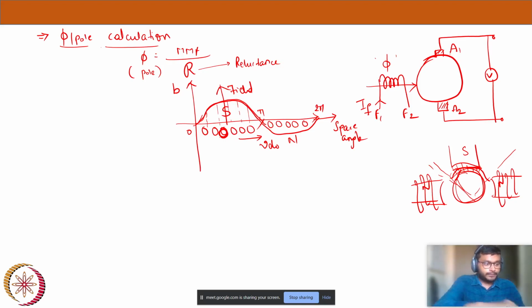Okay, sir, I am taking it individually. Yes, if you remember it individually, at some point you might forget. Go with the basics. If you want to know the direction of induced voltage, that will be useful for a generator, because you apply the field first, then voltage is the effect of it. Here the cause is field. So in that way, you know you have to use the right hand rule for the generator. That's how you should remember it. Okay, sir, clear.